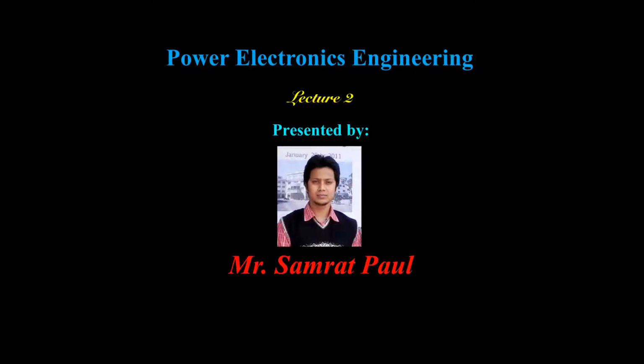So, in this lecture session 2, we are going to demonstrate the topic on Thyristor turn-on methods. Before going into this lecture session, we should recall the previous session in which we studied the VI characteristics of Thyristor, in which we found that the Thyristor can be turned on by application of a huge amount of anode voltage that is above VBO, or forward breakover voltage, without application of the gate. And when the device starts conducting and the device current, or anode current, reaches the latching current, that is IL, then we can say the device is in the on state.